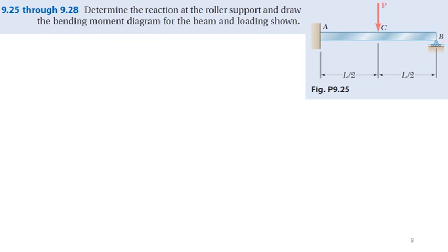Okay. So the equation of elastic curve for section BC, what we have. So that was EI y. Since C3 and C4 are 0, we have MA x square by 2 plus RA x cube by 6 minus P by 6 times x minus L by 2 cube.